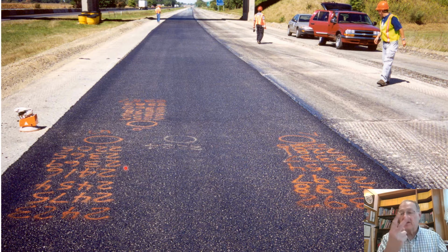Another pass, 369. Almost nothing. Okay, so let's do 2 breakdown passes. Let's let the temperature come down about another 50 degrees, and then we'll do the intermediate rolling. First pass of the intermediate roller, which again was a vibratory steel compactor, and it goes from 369 to 416. Pretty good jump. 416 to 454. Pretty good. 454 to 475. Still good. 475 to 423. Oh, hold on. It broke. Okay, so we're not going to put this pass on.